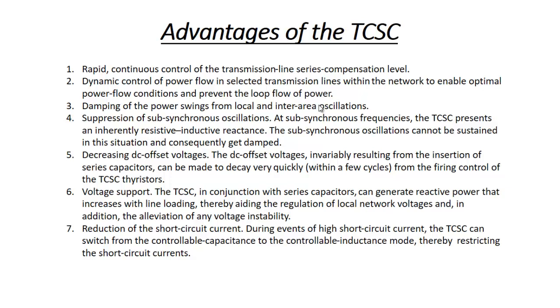One more thing, suppression of the subsynchronous oscillations. This is one more thing which I did not explain here: what the subsynchronous frequency and subsynchronous resonance or oscillations are. But for the time being, you should just keep in mind that it results in the suppression of these oscillations. At subsynchronous frequencies, the TCSC presents an inherent resistive-inductive reactance. The subsynchronous oscillation cannot be sustained in this situation and consequently gets damped. These also result in damping of the subsynchronous oscillations.